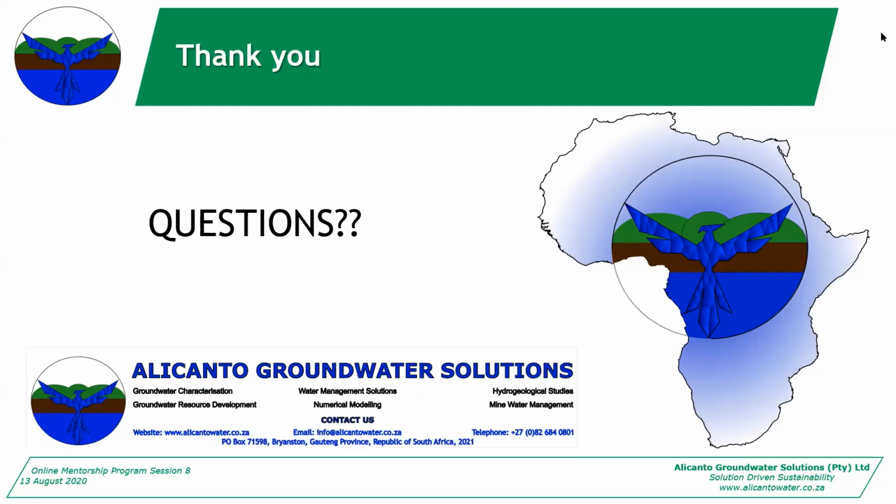And then just one question from my side is, one thing we didn't touch on is the difference between numerical analytical models and interpolation. There was a query regarding a landowner. He appointed his own consultant and we had to review the reports from his specialist, and they actually used interpolation, just normal groundwater level interpolation, and let's say sulfate concentrations, and they just interpolated that and presented that as a model. For somebody like a farm owner that doesn't necessarily have a background in all of these things, he presented that to us and said, this is a model that my consultant created, but it was just basic interpolation, and didn't take into account any hydraulic properties.